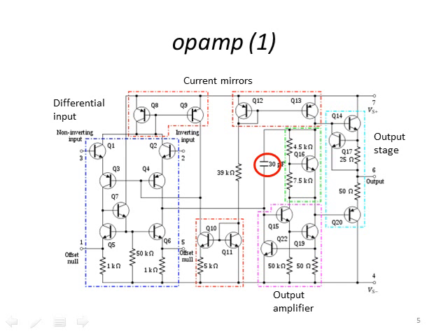And the capacitor circled in red in the center is called the Miller capacitance, and this is basically a tuning capacitor to set the stability of the amplifier, because we have a lot of capacitors within this system, and we want to be able to set the frequency response and the phase response of the system so that it operates in a stable regime.